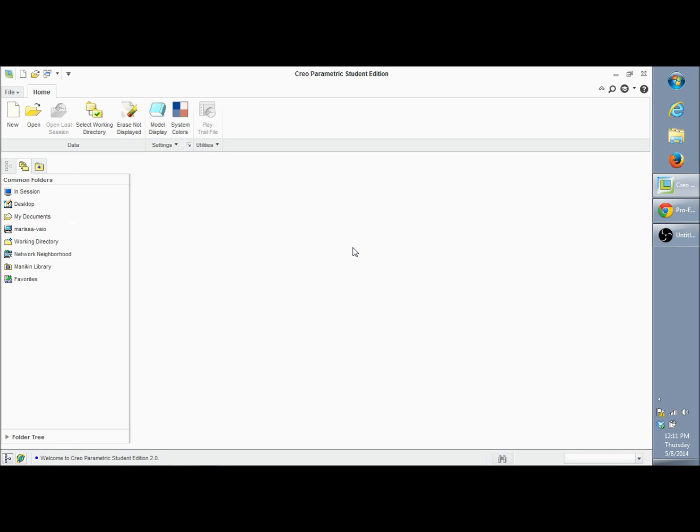Your chosen feature around in the part. Within assemblies, they are used to create a pattern of certain parts or other assemblies that you have. So say you have a plate with a screw hole pattern, and you want to put screws into those holes in the assembly. If it follows a certain dimension or revolves around a certain axis, you can easily create a pattern. You just use the pattern tool to insert one screw, create a pattern, and then pattern it around a certain axis.